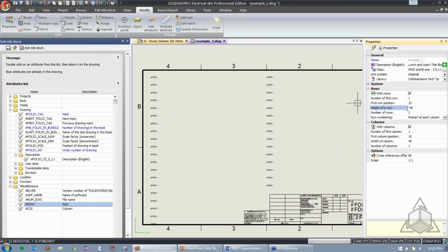The height of each row, and this is where I use my array setting, is going to be a setting of -0.5. So my first row is up top, and I'm going to go backwards, -0.5 down to 0, 0. So go ahead and type that in. -0.5. There we go. Gotta have that 0 in there. And then my number of rows. So based on my array, I know I have 20 rows placed in here.